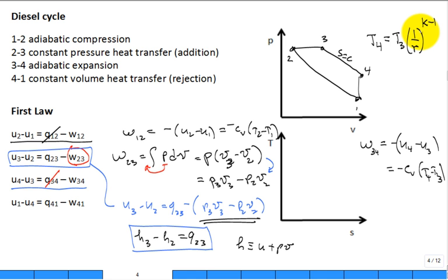Are you familiar with that? Right? So you had to solve an Otto problem. You're using that ideal gas relation, constant specific heats, isentropic process, how temperature and volume are interrelated in an equation. Well, here we're not compressing. What we're doing is we're expanding, and so there's the change right in here.